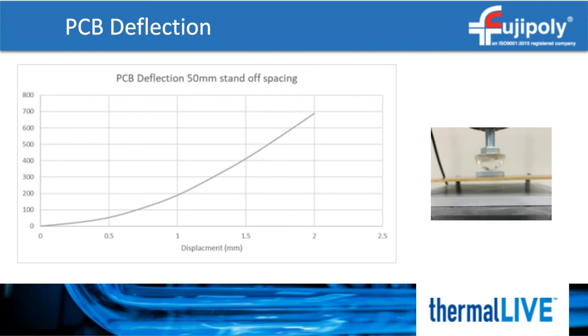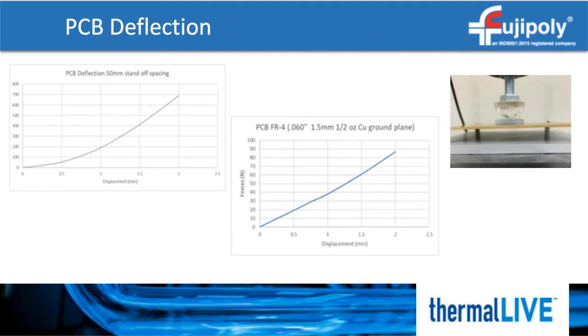On this slide, we can see both the 100 millimeter by 100 millimeter PCB standoff sample, as well as the 50 millimeter by 50 millimeter PCB standoff. Big difference. The force required to deflect the PCB is now a fraction of what it was previously.